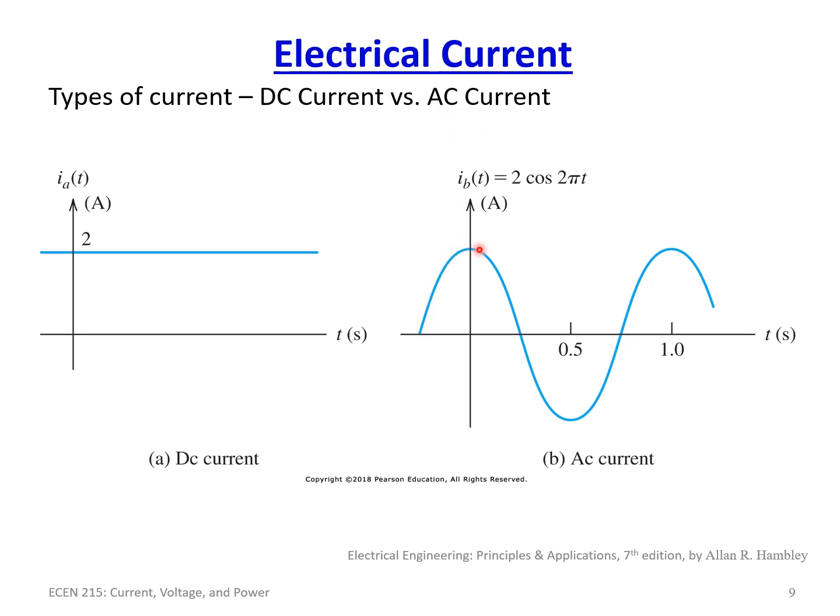So as you can see here, we have a signal that is constantly changing. It actually has a cosine component. And so it is alternating back and forth. If you sum this together, the sum is 0. Because if you take the average of the signal over time, it will be 0 volts or 0 amps, depending on if it was an AC current or an AC voltage.